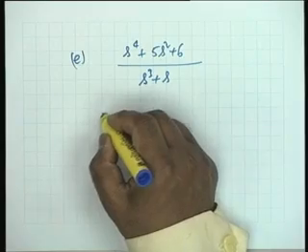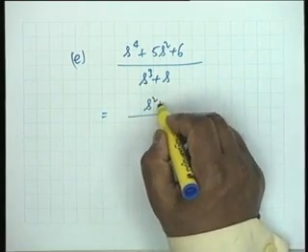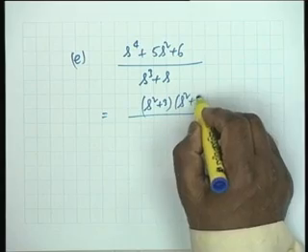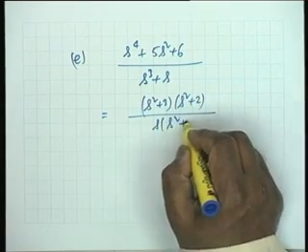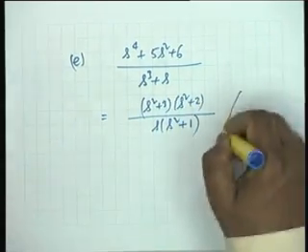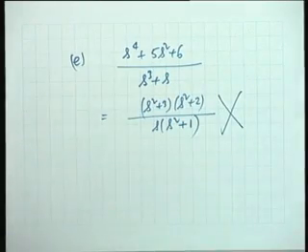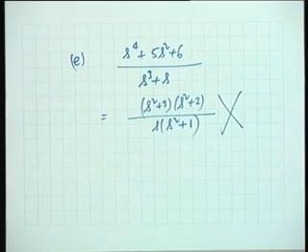Oh, I am sorry. All right, then we require a consideration. I am sorry, I ignored the... It is LC. Let us write it down. (s squared plus 3)(s squared plus 2) over s times (s squared plus 1), because poles and zeros do not alternate. Can we say that this can still be PR? Can this still be PR?